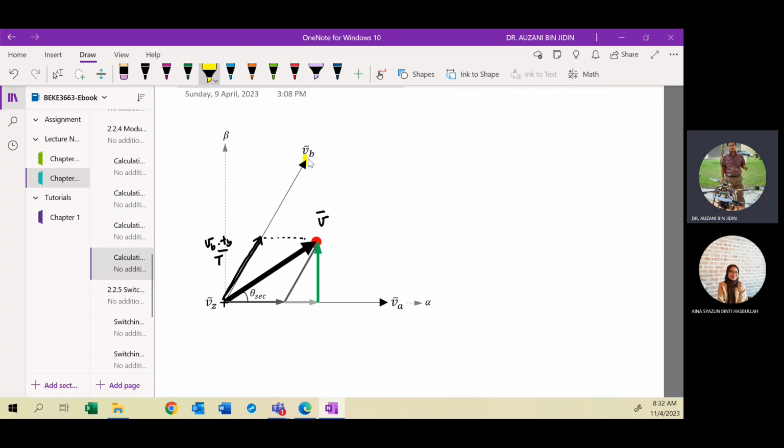So where your space vector here comes between the adjacent vectors VB and VA. So here is the component of vector. You can state the equation as VA multiplied by its ratio, TA divided by T, plus the zero vector. Remember your zero vector is located at the origin, where the D and Q components are zero. So here you have VZ and its ratio, TZ divided by T, where the value is zero.